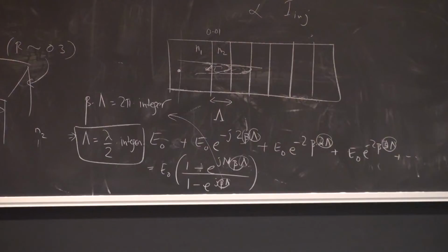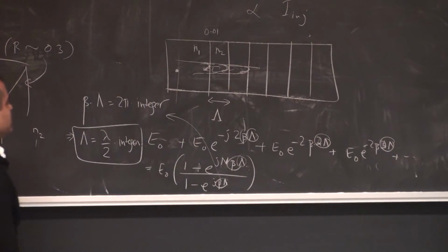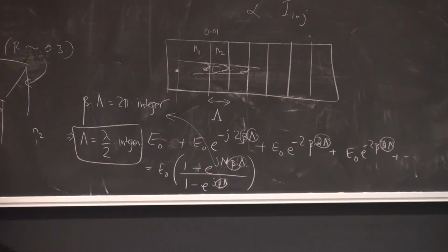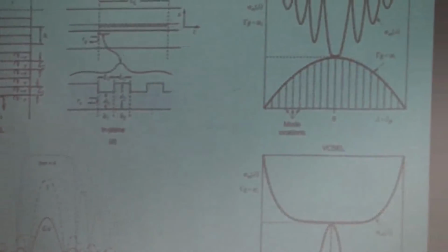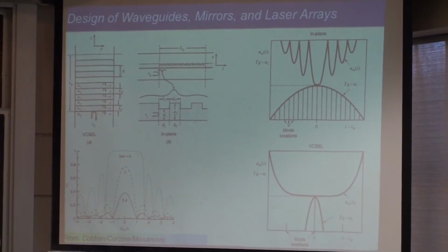Quite a bit of design goes into this, choosing the right refractive indices and the right thicknesses. But as long as you meet the criteria, you can get a narrow band over which you get 100% reflectivity, and that's a great mirror for direct on-chip integration.